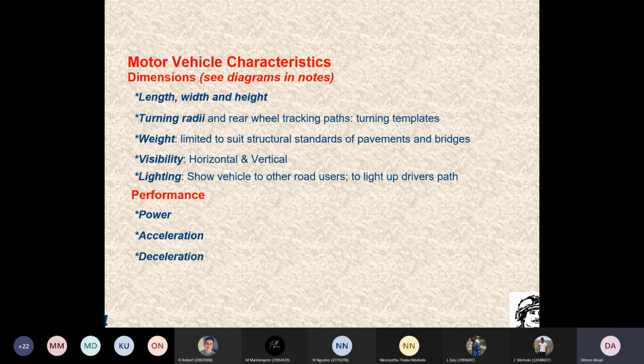Okay, so now we're looking more at the structural design aspects, pavement design. I'm not sure whether you covered it in 2B. You may have covered pavement design there, different methods. The South African method, the road TRH4, may have covered that. There are other methods as well, CBR method, group index method. So there are various methods. Those are more international methods. The TRH4 method is for local conditions, research by the CSIR, Council for Scientific and Industrial Research. They're based in Pretoria.